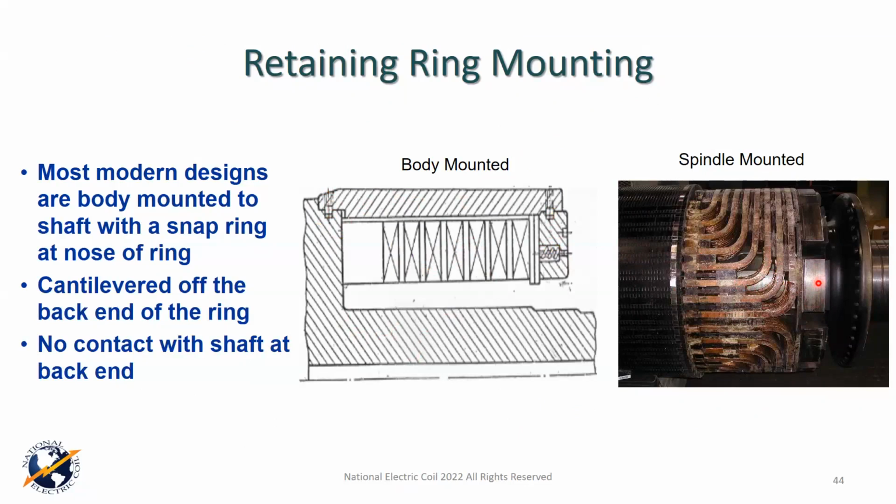Now, one of the things you also need to know about spindle mounted rotors, and GE did come out with some TILs that talked about this, on this design, and the reason it's not used a lot anymore, is that during cycling, as you go up through and down through the speed range, the flexure of this retaining ring, when you're going through criticals and startup and shutdown, the flexure is happening out here because this is your shrink fit.